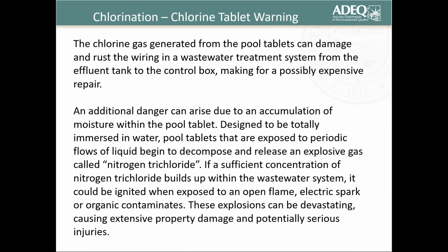Now, let's look a little further here. The chlorine gas generated from the pool tablets can damage and rust the wiring in a wastewater treatment system from the effluent tank to the control box, making for a possibly expensive repair. An additional danger can arise due to an accumulation of moisture within the pool tablet.